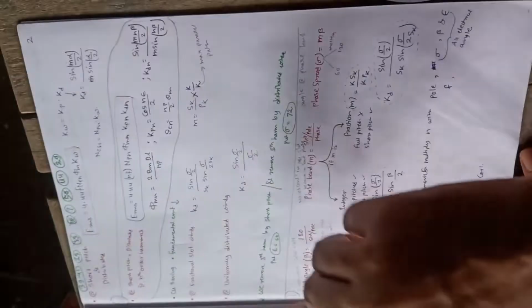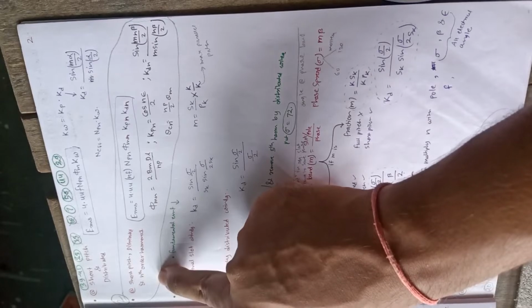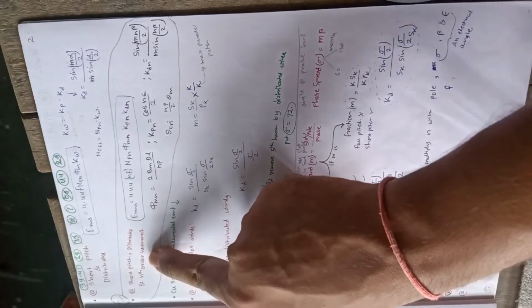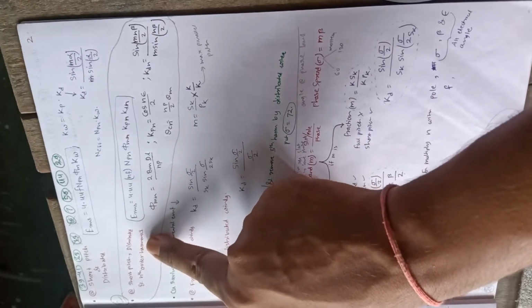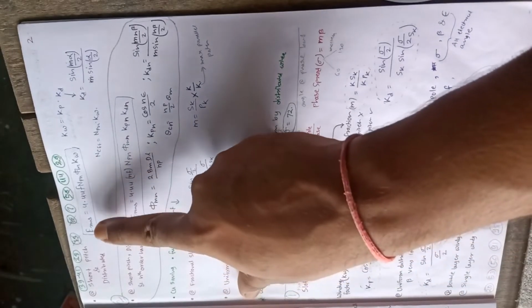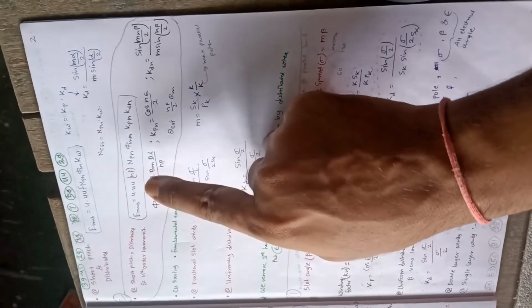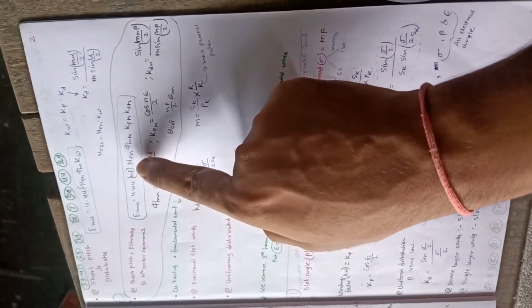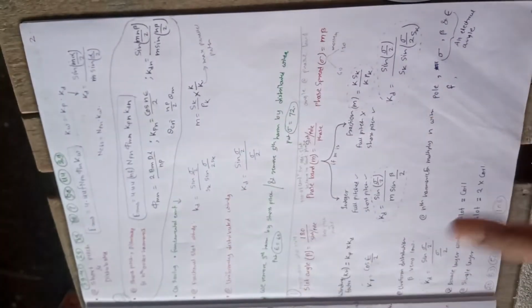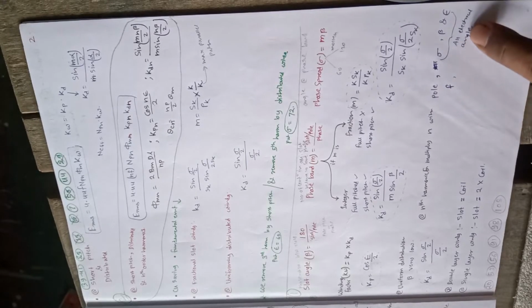Okay. And next we have when we do short pitching plus distribution plus removal of the nth harmonic. If we do all these three things, then we have to use the same formula. What we have to do is introduce a multiplication of n in the factor of frequency, in the factor of pole frequency and all electrical angles.